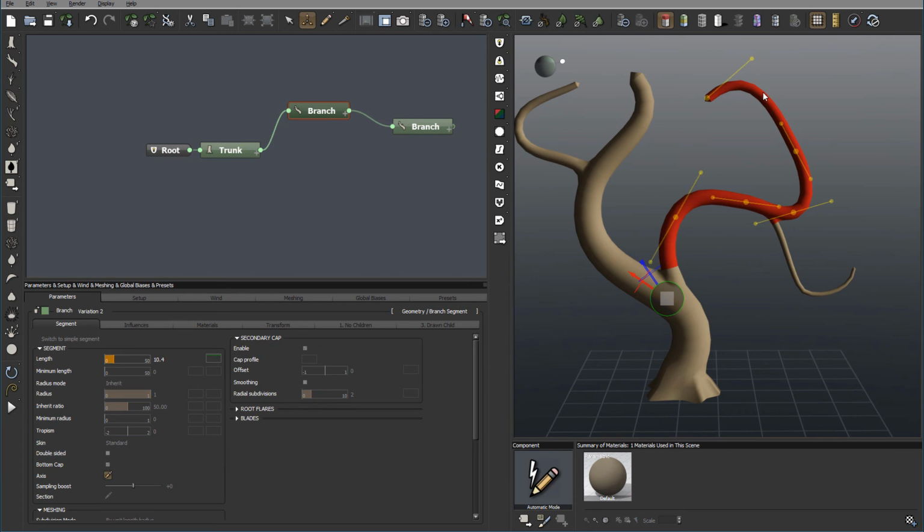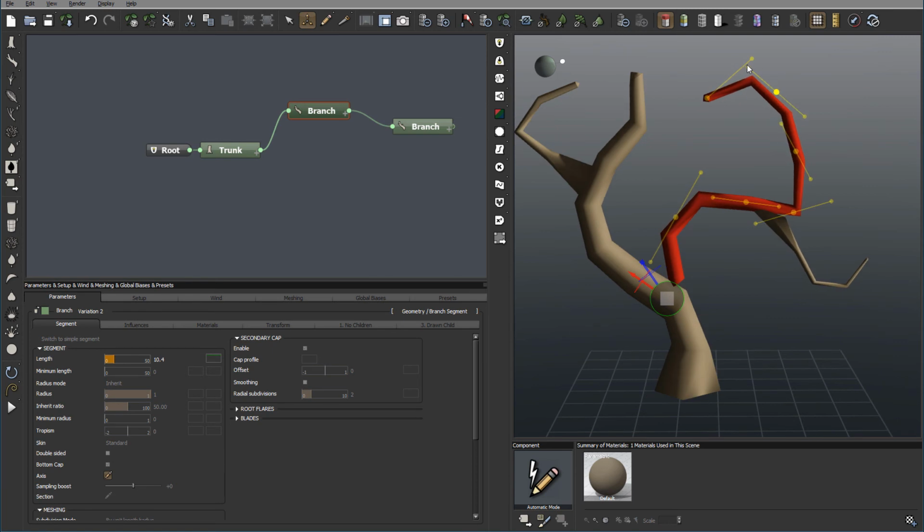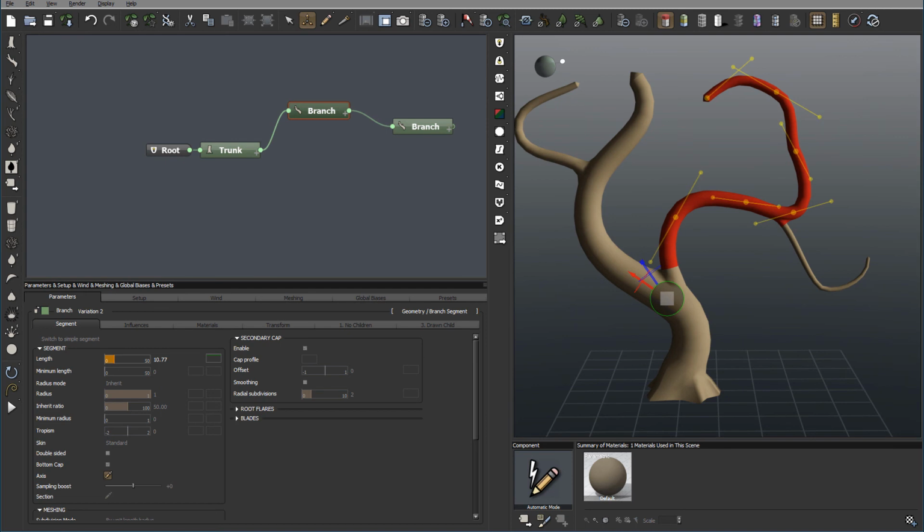Also, we can add additional points. We can press Shift and left click, and it will add an additional point if we need to add more smoothness or rotation in other areas. If we need to remove a pivot point, all we need to do is right click, and it will remove the spline point that we just created. So this way we can modify and adjust.